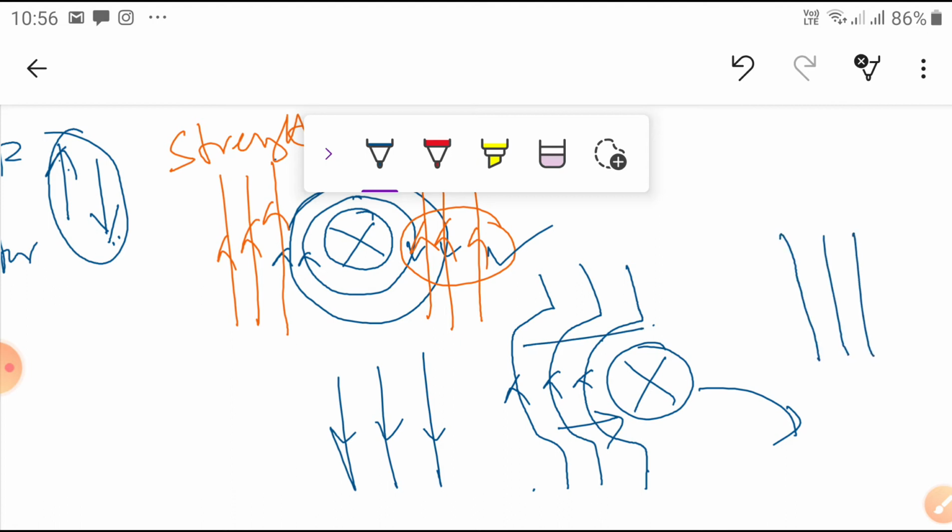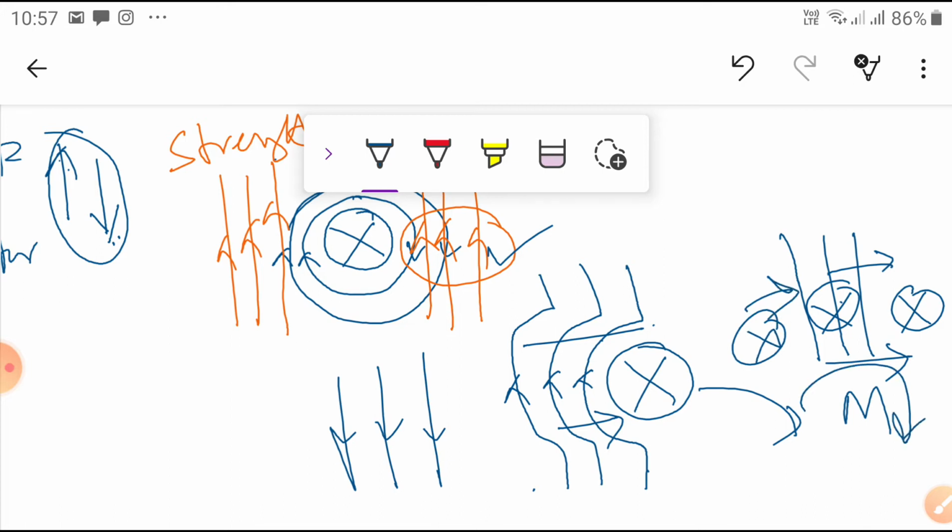The conductor is moved from this place to this place, that means moved in a clockwise direction. That is nothing but mechanical energy generation, torque is developed. Next, another conductor comes here, it will also move in this direction. Another conductor comes here, that will move. So there is a torque, and rotation takes place. Okay, so this is the procedure of how the torque is developed in the induction motor.